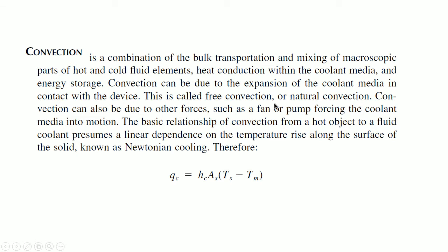forced convection. In the case of natural convection, the expansion is the one that aids it. But the reality of natural convection is that the orientation of the fins is critical. It should be in the same direction in which the fluid is flowing. In the next picture, I will show you a printing head which moves in a printer.